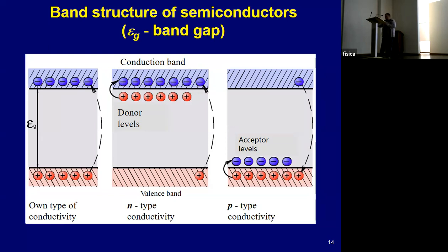In the transition region, the concentration of equilibrium charge carriers is several orders of magnitude lower than in the rest of the bulk of the semiconductor. The transition region is the main working region of a semiconductor detector. In the absence of external voltage, the extent of the depleted layer is very small, on the order of a micrometer. However, the width of the depletion region increases when so-called reverse bias is applied to the p-n junction. The external voltage is connected in such a way that minus is applied to the p region and plus to the n region.